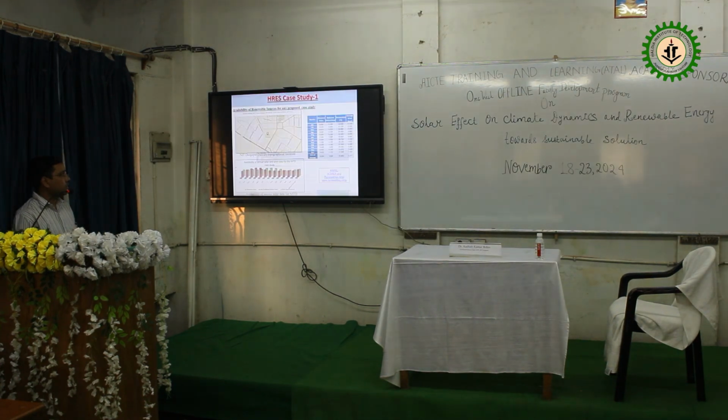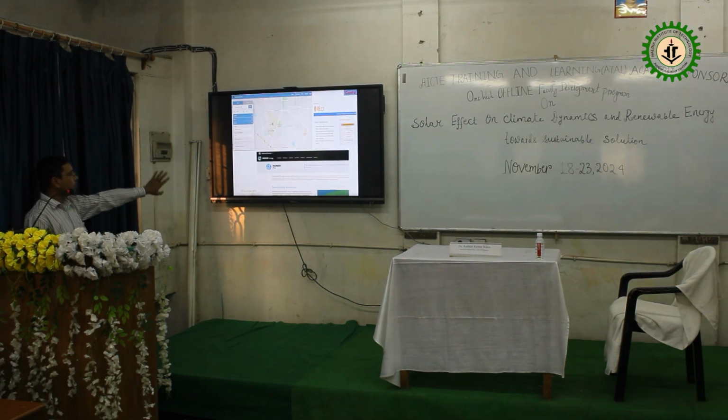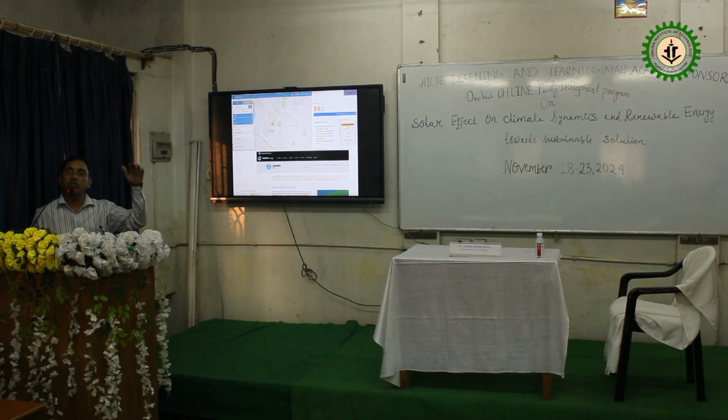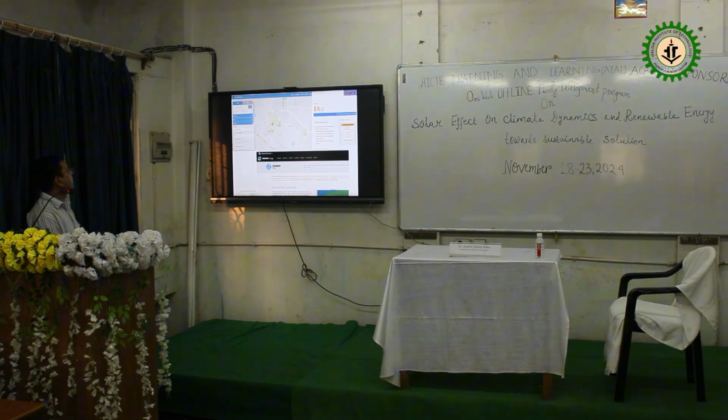So another software, this is the Homer one that I have done. Other software also I have given, Renewable Ninja and RES, and that is the Homer. Sensitivity analysis also you can do with the variation, it means time series analysis with the variation of the radiation, what will be the impact. It means for the annual analysis within the time series for the 8760 hours. If you want to do it for 24 hours, you can do that also. Okay. We say Homer site. What is available here?